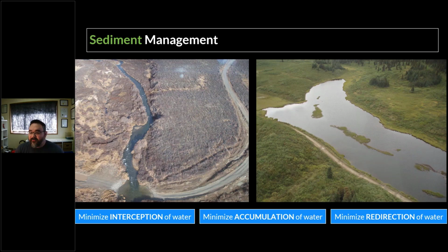Clearly not by fording creeks as in the left-hand picture, but even when you're right beside a water body, how can you minimize sediment delivery through your road grades, like we spoke about before, or putting swales in the grade in places where you have more room for that water to filter before it hits the water body, or just choosing a slope or a side of the water body that has less erodible materials, or is gentler, where your cuts and fills aren't going to be big.